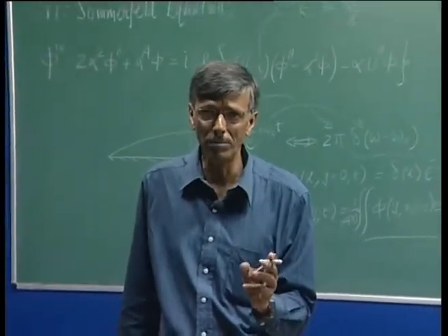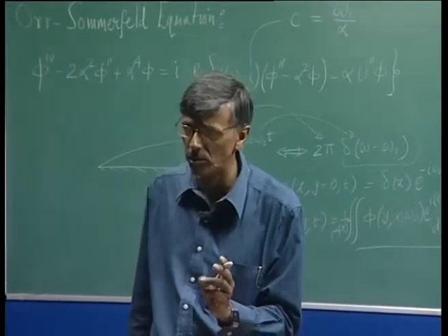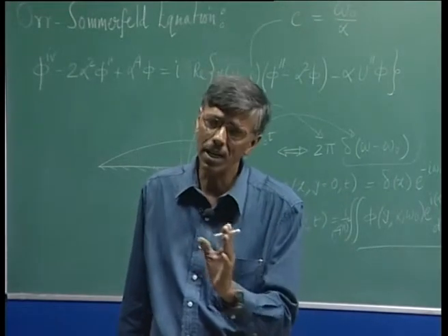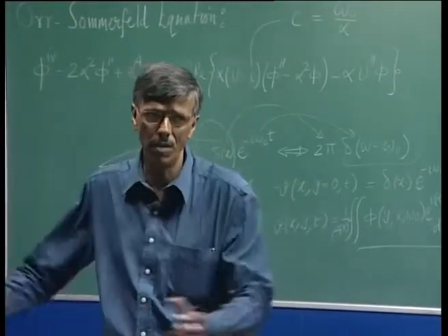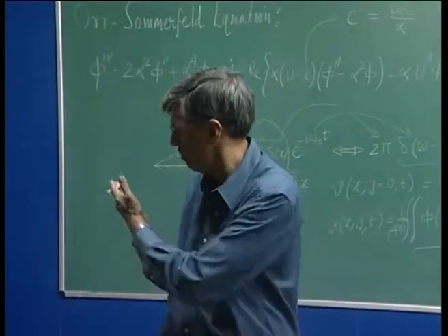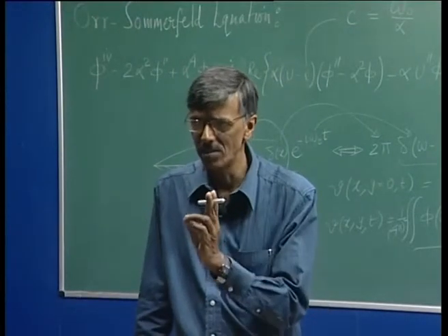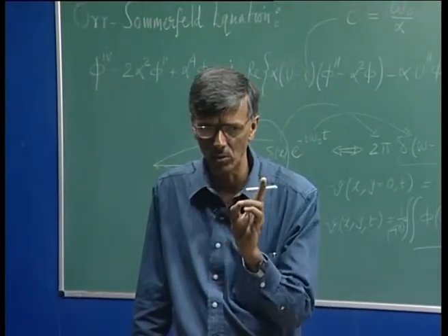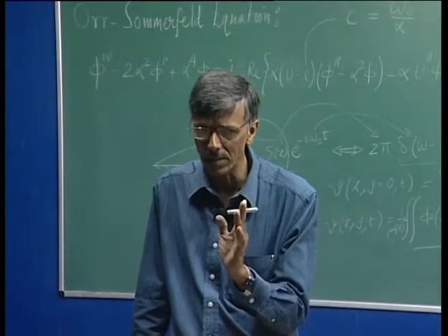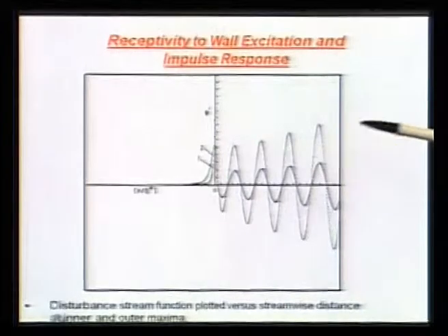So, what happens is alpha I negative values, if they are there, then you are going to see it everywhere, all x. But what happens in a realistic flow like what we are studying here, even a Blasius boundary layer, these points are very close to the origin. So, what happens that you are going to see a kind of a moderate growth.